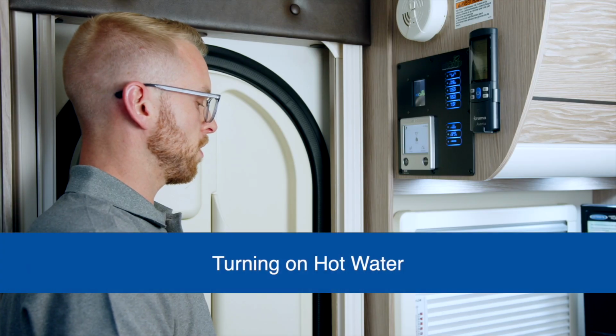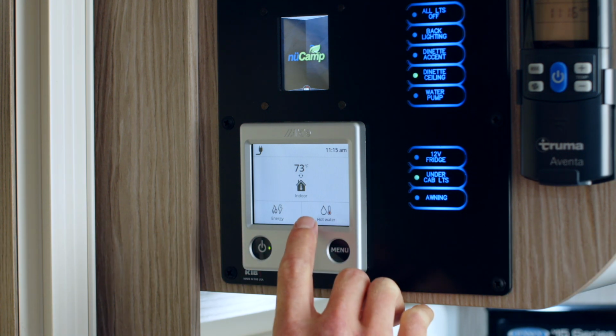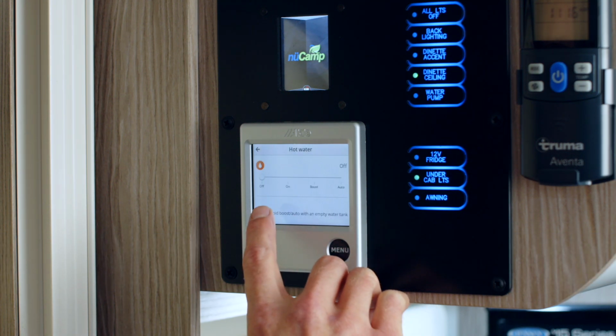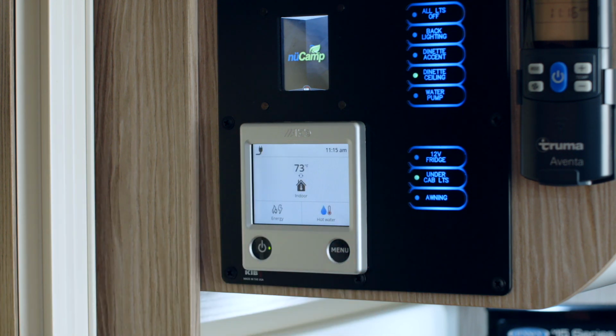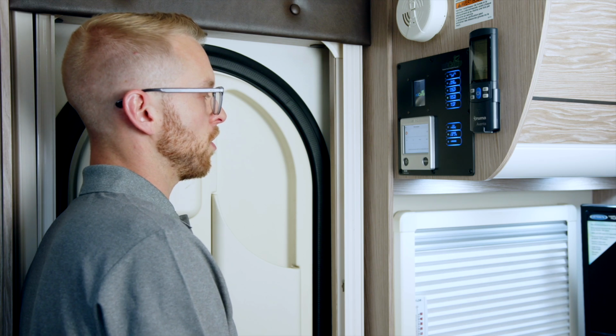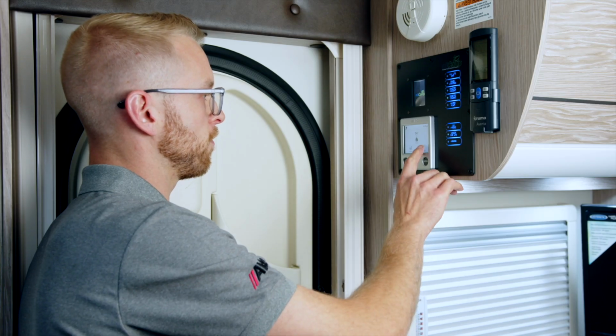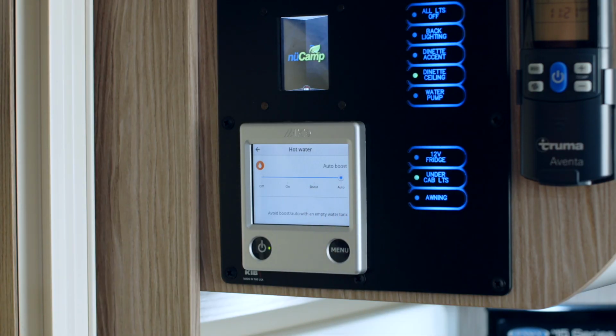The status screen of your Alde control panel shows which hot water mode is active. When the droplet is solid blue, that means hot water is on. If your RV is equipped with the Alde 3030 Plus, you will also have the Boost feature or Auto feature. Move the slider to Boost to activate the Boost function. This will prioritize hot water production for the next 30 minutes. The Auto function will activate Boost when the water temperature reaches a certain set point.